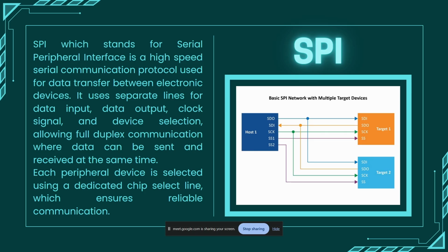And then it's also a two-lane highway. It's like UART. Bro wants to talk to the module and also receive data from the module simultaneously. So you have a data input line and you have a data output line. And then you have a clock signal so that bro also gets the advantage of I2C, that you're never reading the intermediate value in the transition of data.